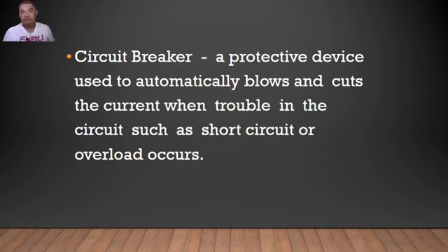After you manage to fix the fault, the overload or the short circuit, you can turn on the circuit breaker again. You don't need to replace the circuit breaker, compared to the fuse. Once a fuse has blown out during a short circuit, you need to replace it with a new fuse on the circuit after you have fixed the fault.